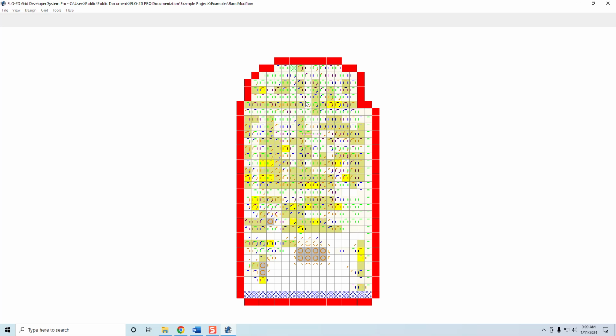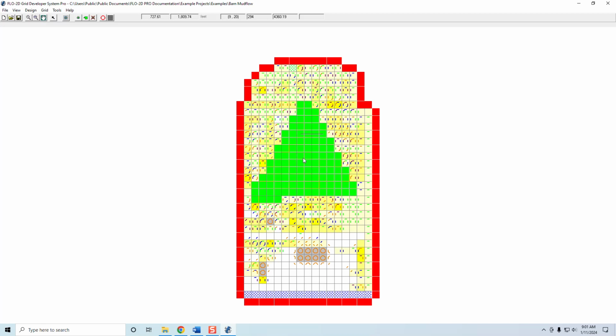That means it can access a DLL that can create a grid layer. Then I will just click a couple of vertex points and double click to close the polygon, and some cells were selected, and that is the second test passed. That means that another DLL can be accessed and is functional.